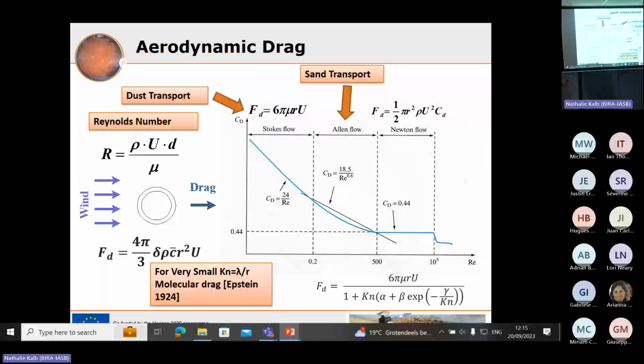So that brings me to drag. Drag on particles as well as drag on surfaces is not a trivial subject. It's somewhat more complicated in the sense that as you change scale and pressure, you go through different drag regimes. So for big things like footballs and people jumping out of aircraft, you're in this regime, Newton flow, so it's basically turbulent. Turbulent drag is the dominating thing. But then, so this plot is Reynolds number.